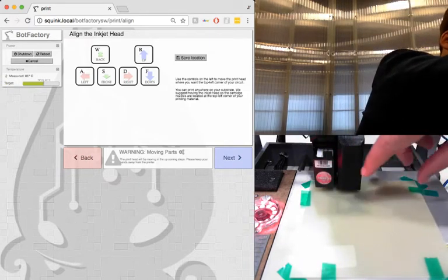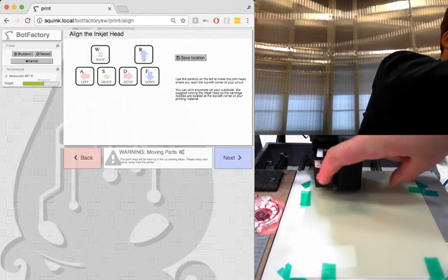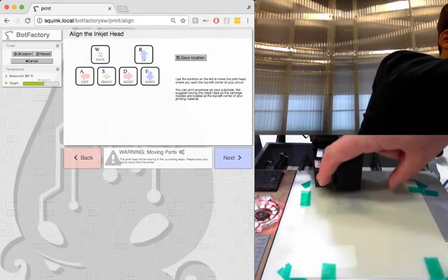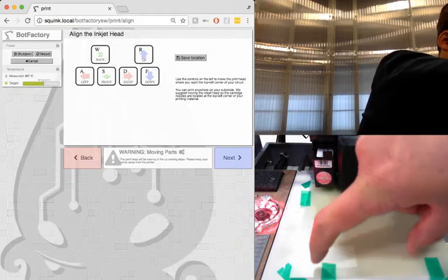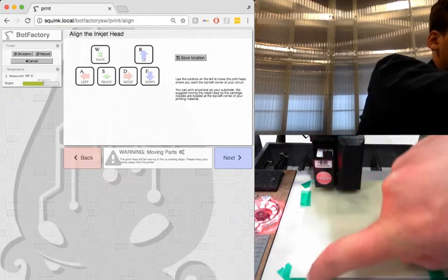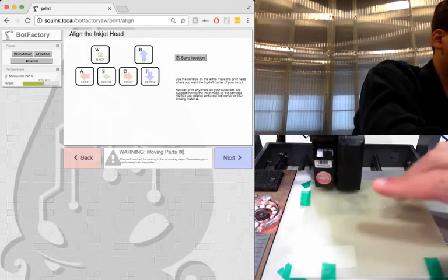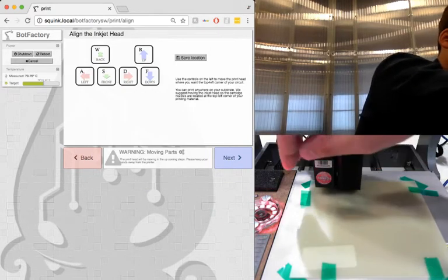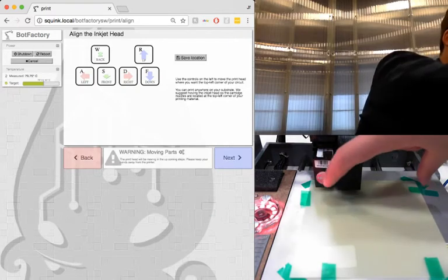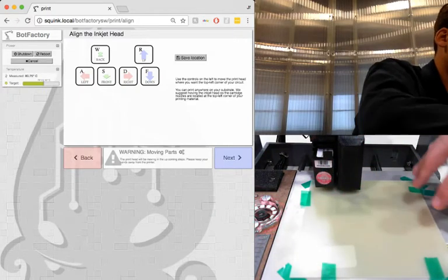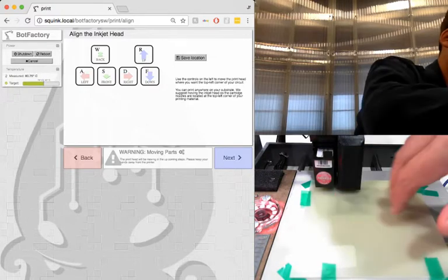So the limited printing area is about 3.25 inches by about 5 inches. This is the area in which you can actually print 2-layer boards. With a single layer, no insulating layer, I can print up to 5 by 5 inches, which is almost the entire size of this substrate here. If I go over, it's going to hit this guy.